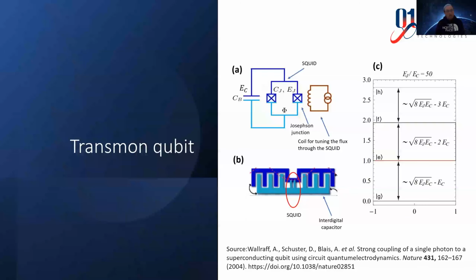One of the promising types of superconducting qubits is called the transmon qubit. The transmon qubit has a transition frequency from the ground state to the excited state at microwave frequencies around 5 gigahertz. Frequencies in the microwave range are appropriate for most solid state quantum devices, also spin qubits. These frequencies are high enough for the standard cryogenic techniques to be used, yet also low enough that fabrication of circuits much smaller than the electrical wavelengths is possible.